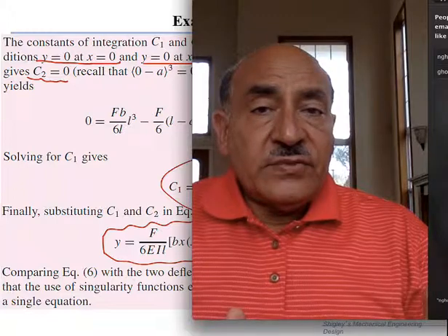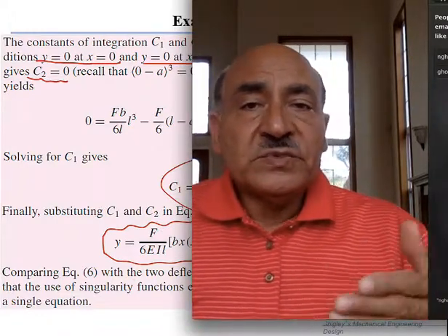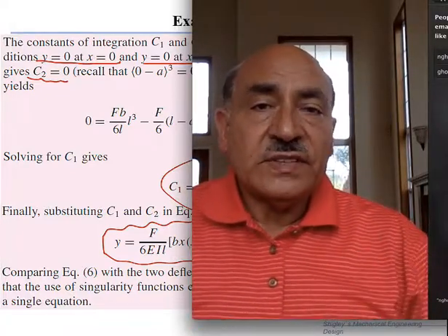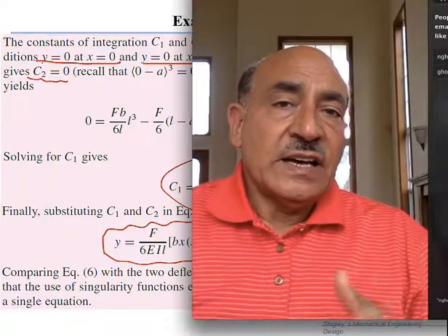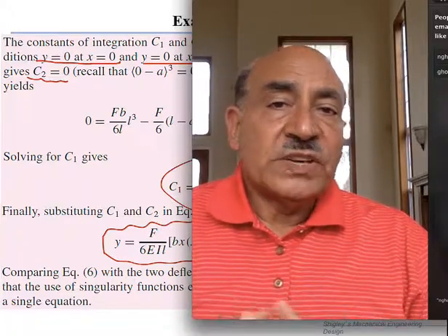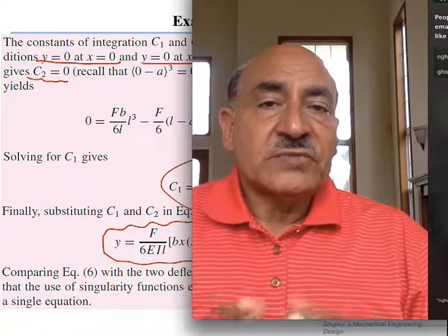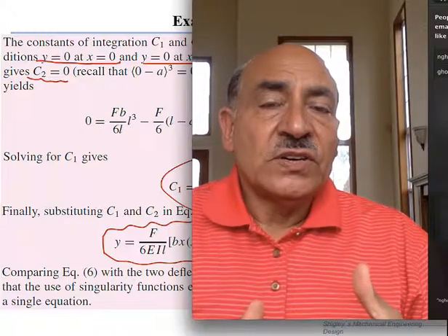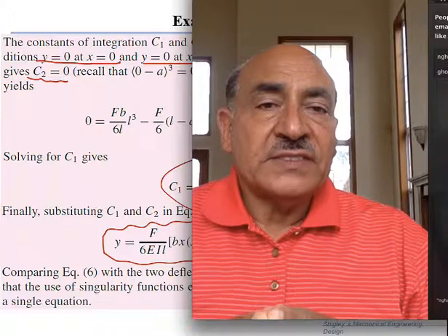So if we just want to summarize, if I'm doing a design, what is my objective? My objective is to find the deflection equation and then to find the maximum value of the deflection, which could be obtained either by differentiation at the point of maximum or by knowing where to look for it from geometry. Another aspect is that we can compute the angle of deflection once we know y prime, because y prime is essentially equal to theta in radians.